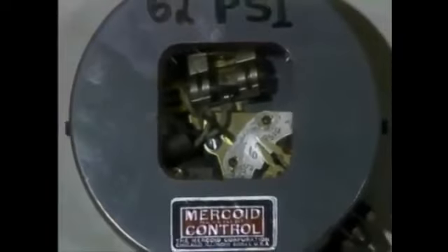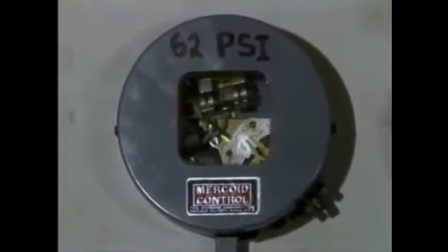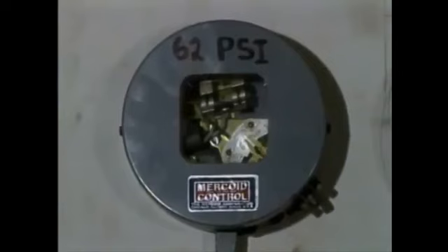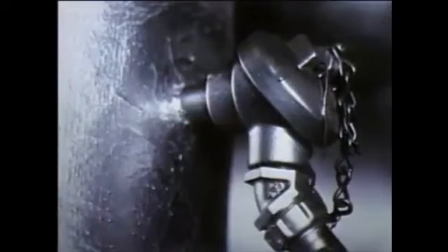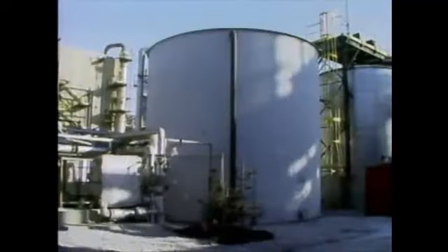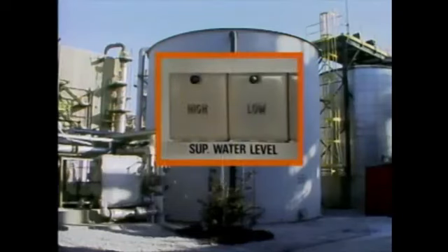Alarms are usually activated by electrical switches, which are operated by sensing devices connected to the process. The sensing device can be mechanical, such as this pressure switch, which uses a Bourdon tube to respond directly to the pressure in a tank. Or the sensing device can be electrical, such as this thermocouple, which generates a voltage proportional to the temperature that it measures. In either case, when the value of the process variable reaches a specific point, the signal from the sensing device operates the switch, which activates the alarm.